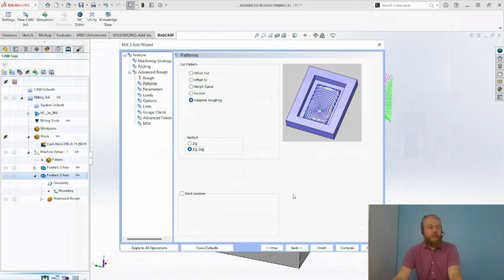Let us know in the comments section if you guys use any of these high-speed machining options. I know that it's best utilized for softer material like aluminum, where the tool can go down to the exact depth of cut and hog out material with a pretty small step over. But with the trochoidal milling, it'll take a lot less time machining than doing all of those depth cuts in different material types.